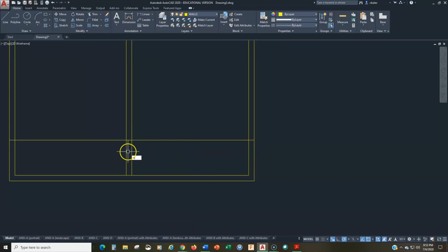All right. Now again, I'm going to trim some of this. I don't want that. Let's trim that over there. This and this. There we go. Okay. And I'm going to extend this a bit here. I'm just going to clean this up because it's starting to get a little messy. This is an exterior wall, so we're going to offset 6.5.